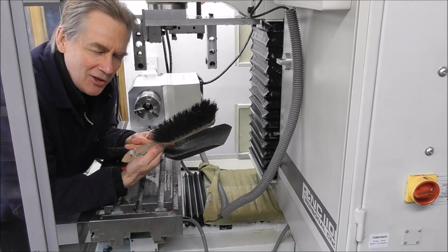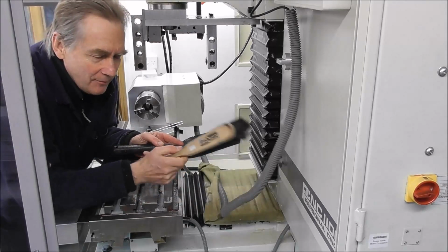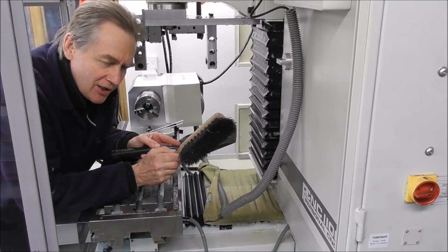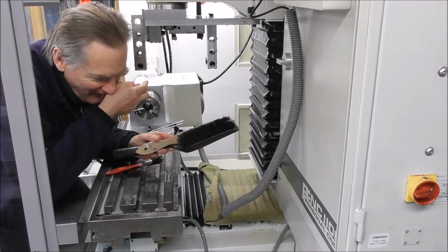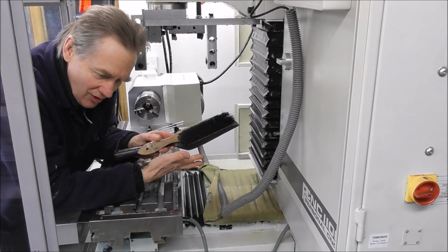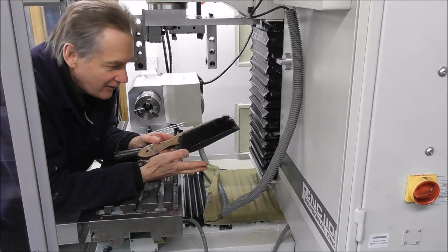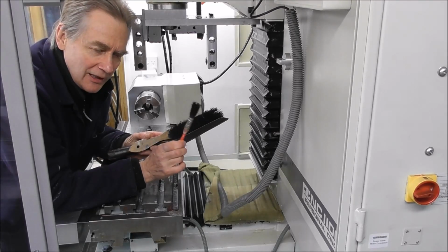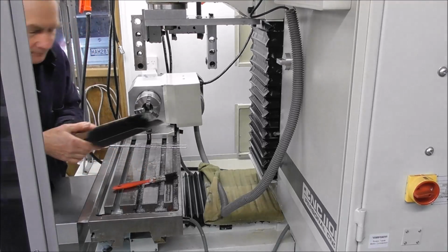It occurred to me a couple of years ago, don't use that brush to clean down your machine, because what you're doing is applying abrasive grit onto your machine, which then dissolves in the cutting oil and ends up in slideways, bearings, ball screws. So just have a brush that's used only for cleaning your machine down. It doesn't get involved in dust and abrasive grit.